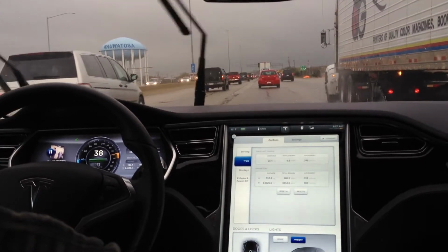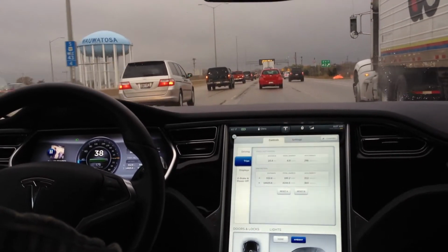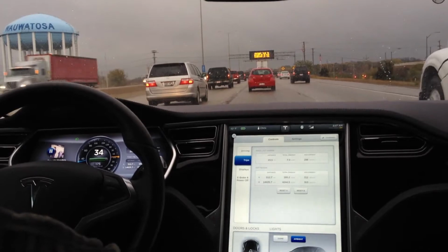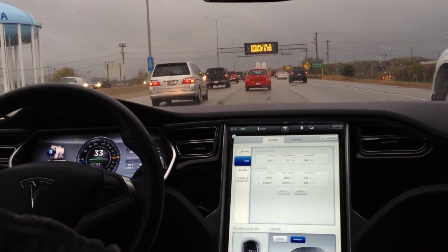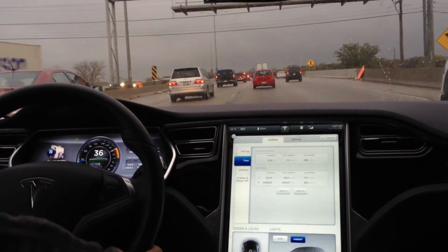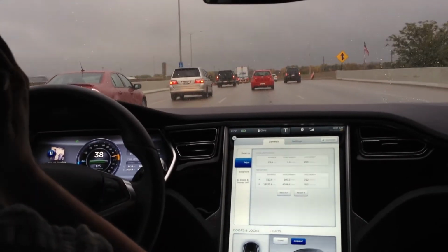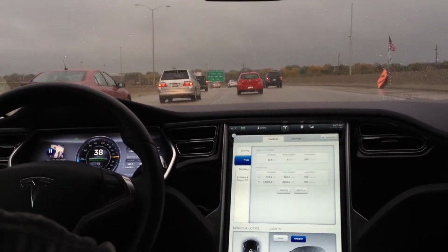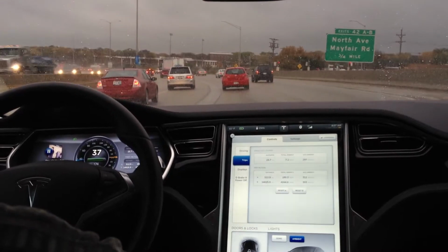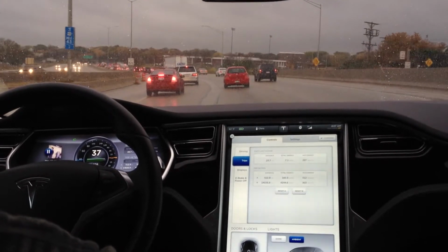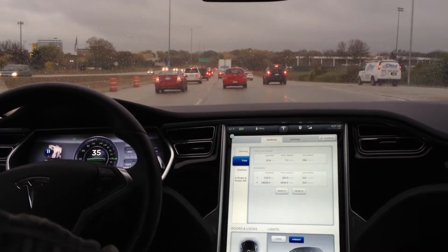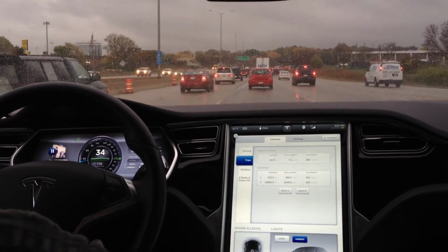So on your internal combustion vehicle, all that gasoline you used to make your vehicle go forward or reverse, depending on how you're driving, to stop your vehicle, all that extra energy is wasted through heat dissipated through your braking system, friction braking. Whereas the Tesla Model S attempts to use as much of that braking power as possible to put back into your battery. It doesn't seem like much, but say I'm charged up to 200 miles, I can get an extra 15-20 miles out of my battery in stop and go driving just from that regenerative braking instead of throwing all that energy away.